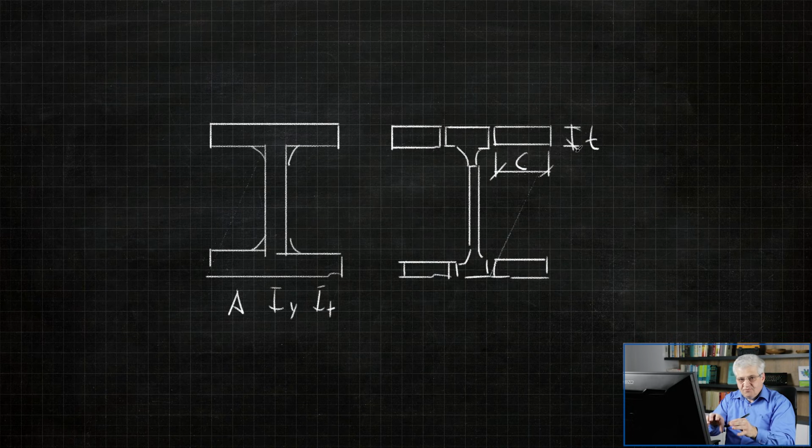For this ratio, there is Table 5.2 in Eurocode 1993-1-1. And in this table, there are limits. So if we have some ratio, let's say 20 or less than 20, we can classify this cross-section part, not the full cross-section, as class 1. If it's more, then it's class 3. And if it's more than, let's say, 80, it's class 4. So there are limits for the classification. Each part gets one class, and the highest class decides the class of the full cross-section. So let's say only one teeny part, let's say the web, is class 4, then the full cross-section is calculated as class 4.